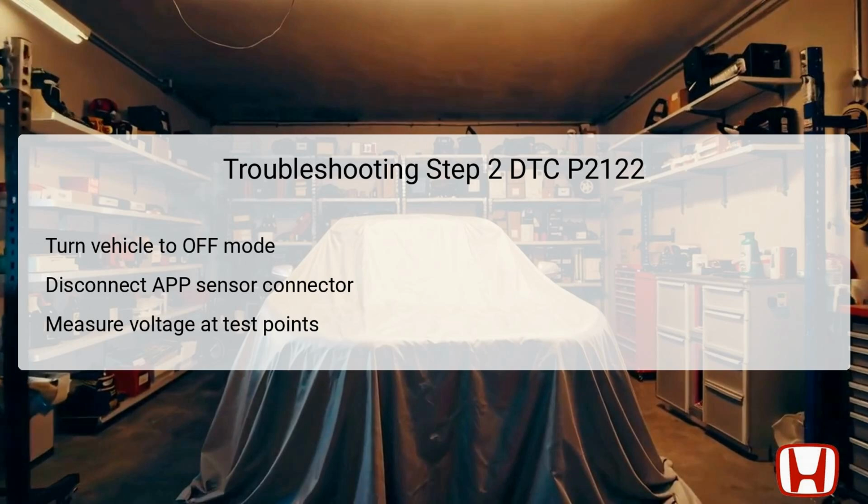Specifically, voltage should be tested between pins 4 and 5 of the APP sensor 6P connector. The technician expects to see a reading of approximately 5.0 volts under these conditions, confirming that the primary power supply to the sensor circuit is operational. If the reading does not meet expectations, further investigation into possible wiring issues will be required.